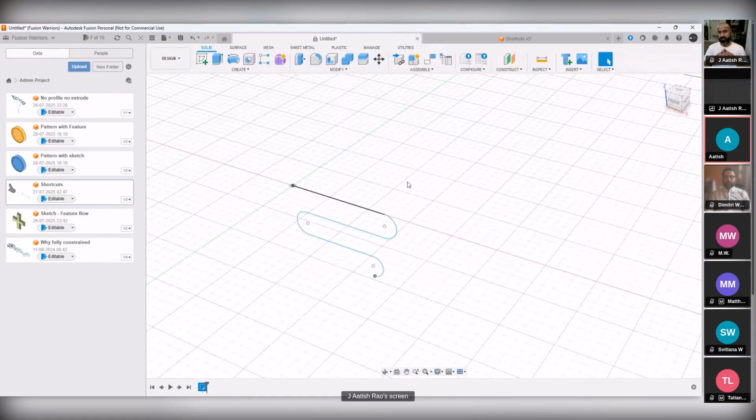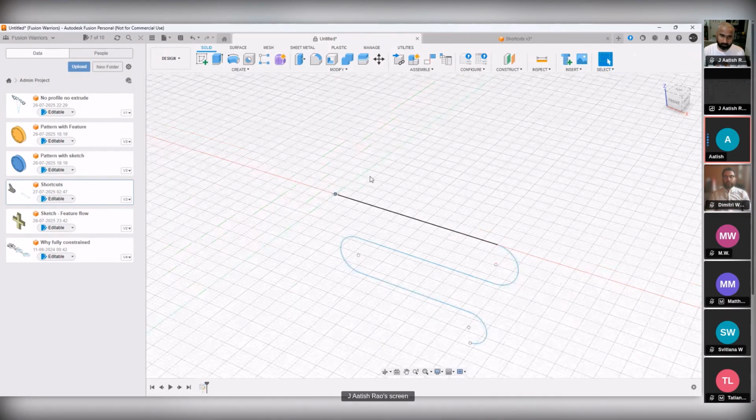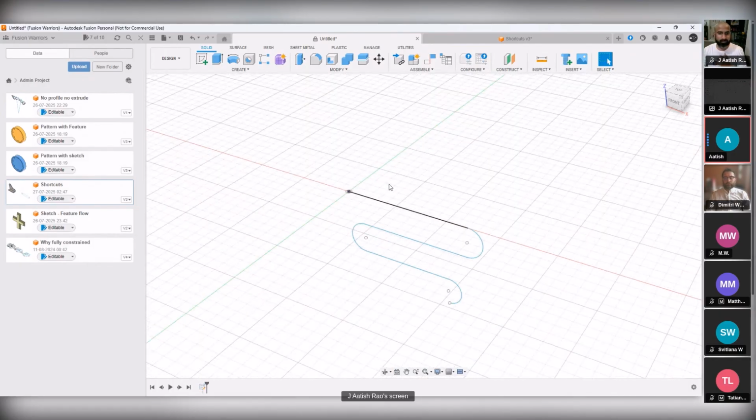keep on doing mistake here is that they don't take care on which plane the path is made and on which plane the profile is being made. So always take care to involve the origin in your sketch. If you're involving the origin in your sketch, you can simply pinpoint where to provide the profile.